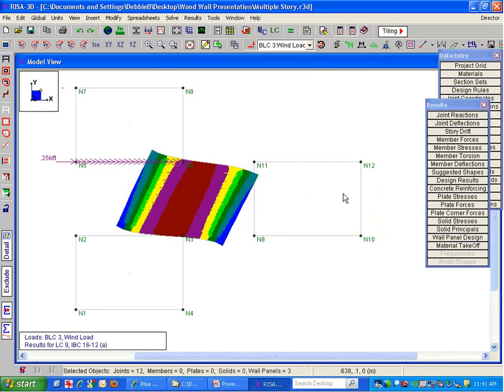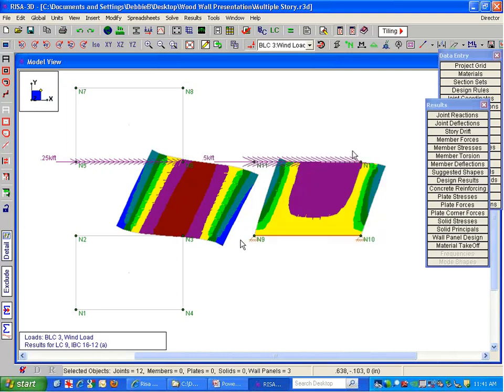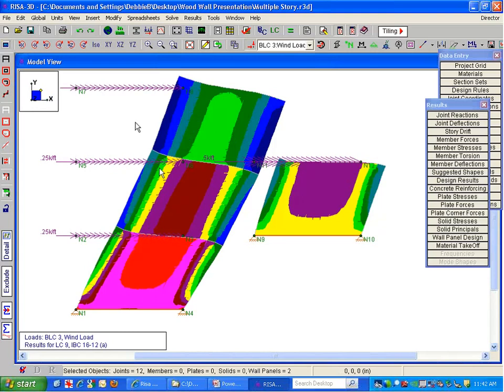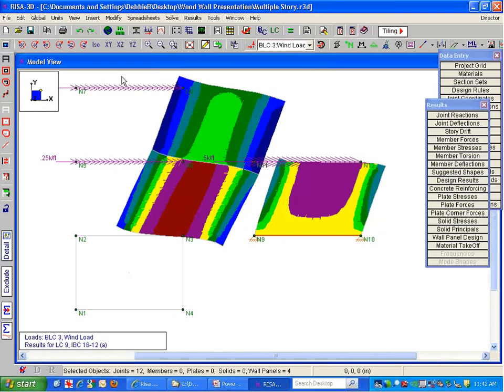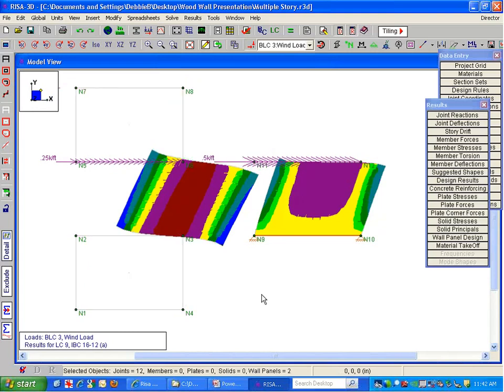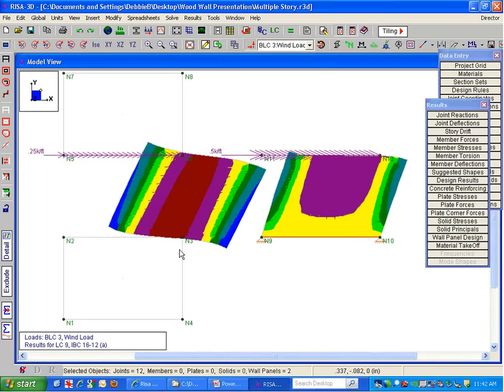And when we tie it down and we do a simple single wall, we don't really talk about rotation, and we don't really worry about rotation. But that may be the difference between that finite element analysis model and your equation value. There's a lot of little things that are happening in a finite element analysis versus your hand calc method, but rotation is definitely not included in that hand calc method.